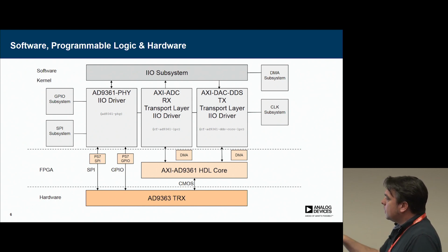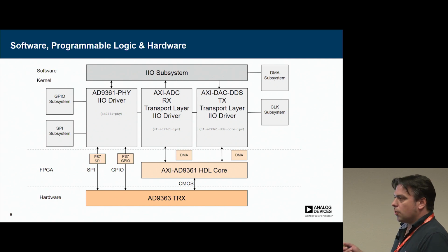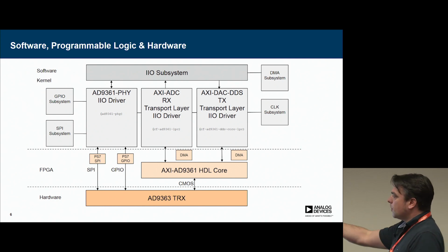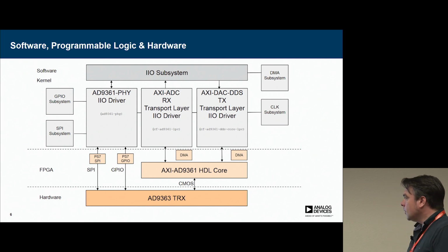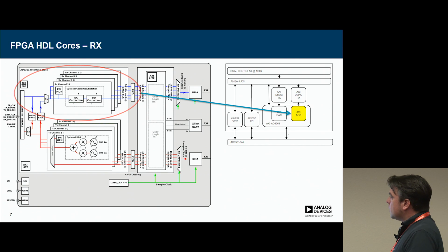We split data and control into different drivers. There's one driver that sets up the transceiver. That's what you use when you change the LO frequency, and the other two drivers are basically for transmit and receive.